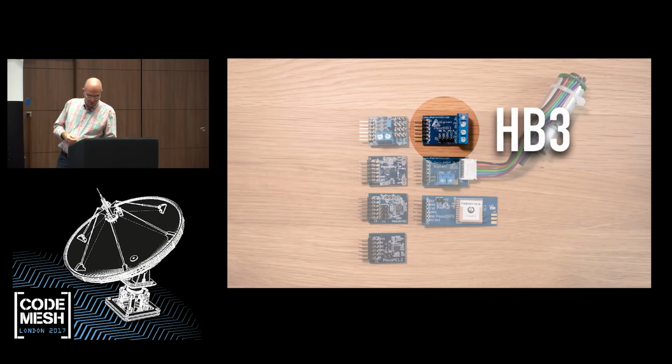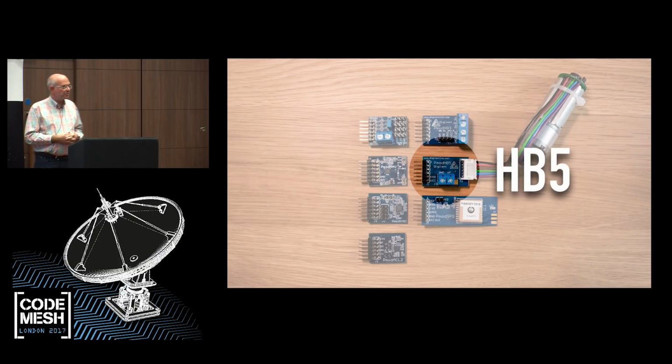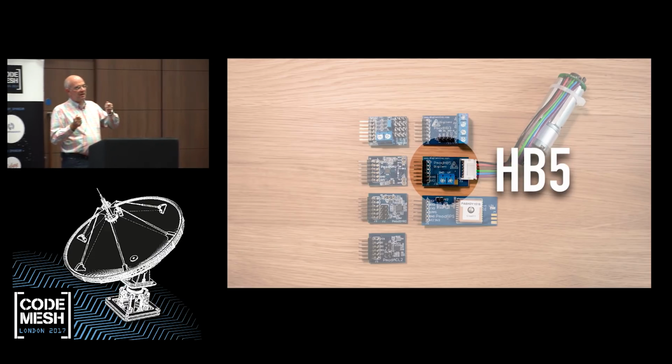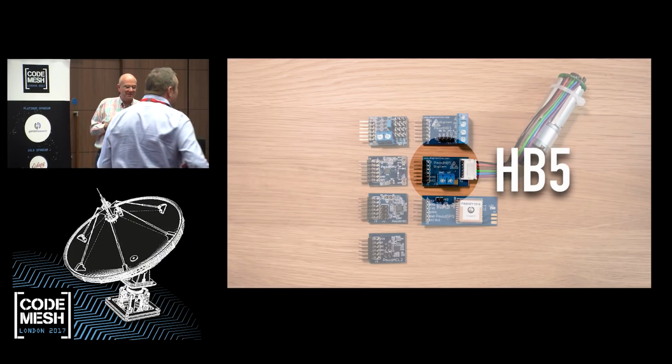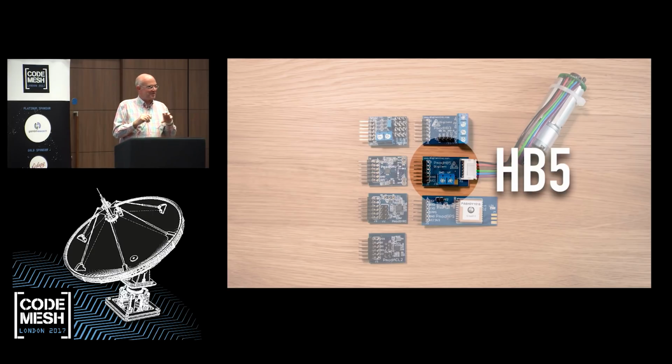and that's another H bridge. An H bridge is a thing to control a motor. By controlling 2 bits, you can say forward, backward, start, stop. And it's very bad if you have start on and switch from forward to backward, because for a very short time you get a short circuit. So we have a driver to take care of this, which stops the motor before you actually switch the direction.